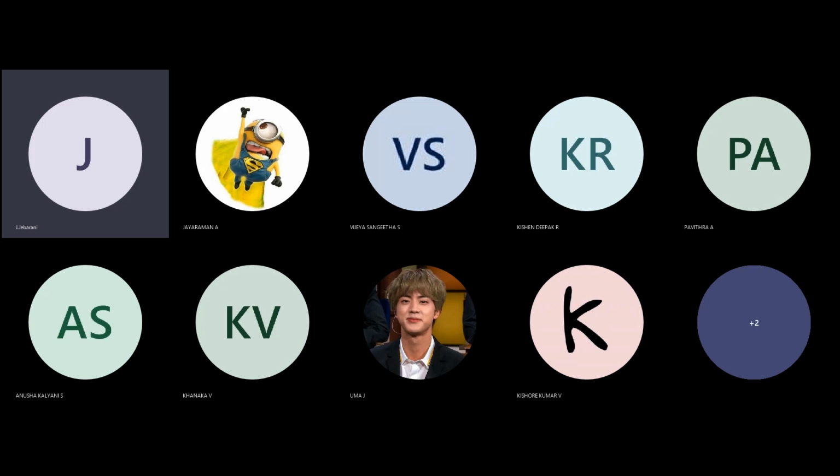The parts produced from the gas assisted technique have smaller flow streams inside the part, so because of the unpredictability of gas behavior, it is very difficult to control the wall thickness of the part. But water makes the wall thickness uniform and repeatable.